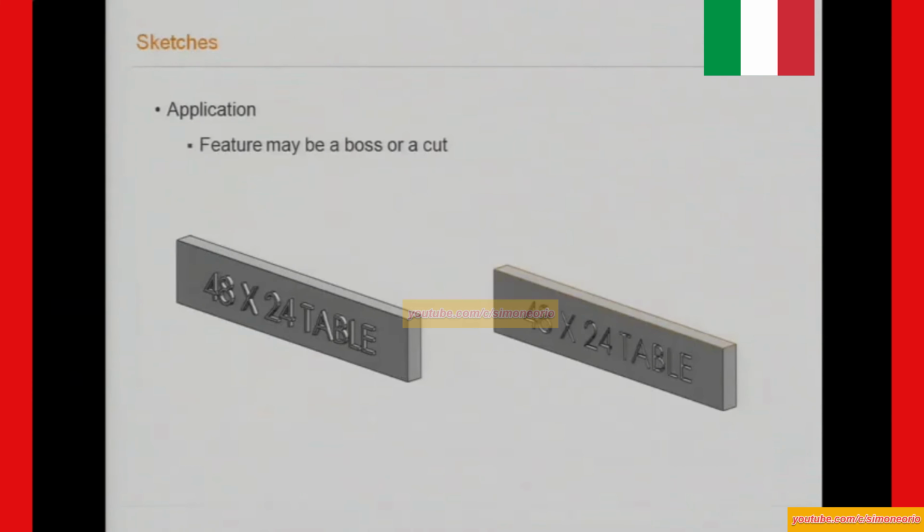The first time you set that feature up, I imagine you made it cut all the way through this part. I did a cut through, correct. Okay, now once you drop that onto your tool, can you adjust that? Say you only want to go halfway. Can you change that? You could cut at a blind distance. Okay. You could change the direction of the cut this way, that way, right? But you really want it to be a cut and not an extrude. Otherwise, you're looking at deleting the feature and redoing it.